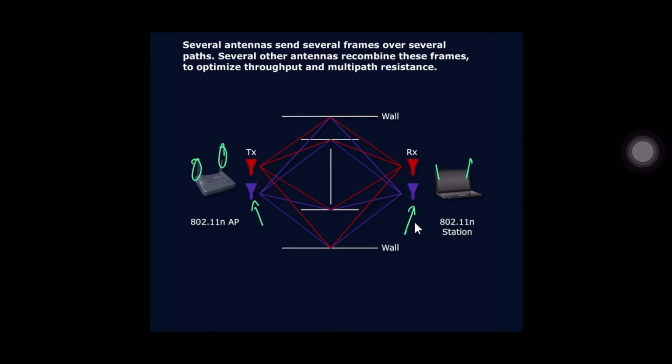Well, it depends. There's a couple of flavors that can happen with MIMO. One is a strategy focusing on redundancy. So let's say I wanted to say ABC, 1, 2, 3. That's my key message that I want to send. So I send out ABC, 1, 2, 3 out both of these antenna. I'm going to redundantly use both antenna to send this data.